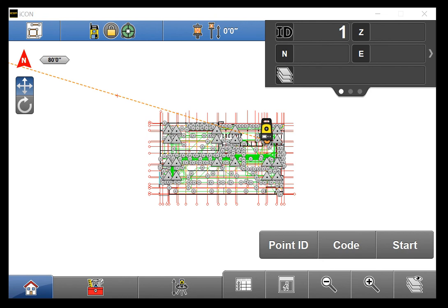Likewise, if I need to see the points that I stored in as-built mode while I'm laying out a deck for any reason, I can toggle on those points through the Layer Manager. Think of the as-built jobs we create in the software as storage drawers. They do not physically contain DXFs and CSVs themselves, even though their visibility can be toggled on. Those as-built jobs are created simply to hold the points stored during the as-built process. You will see examples of file organization and layer management through the course of this video.